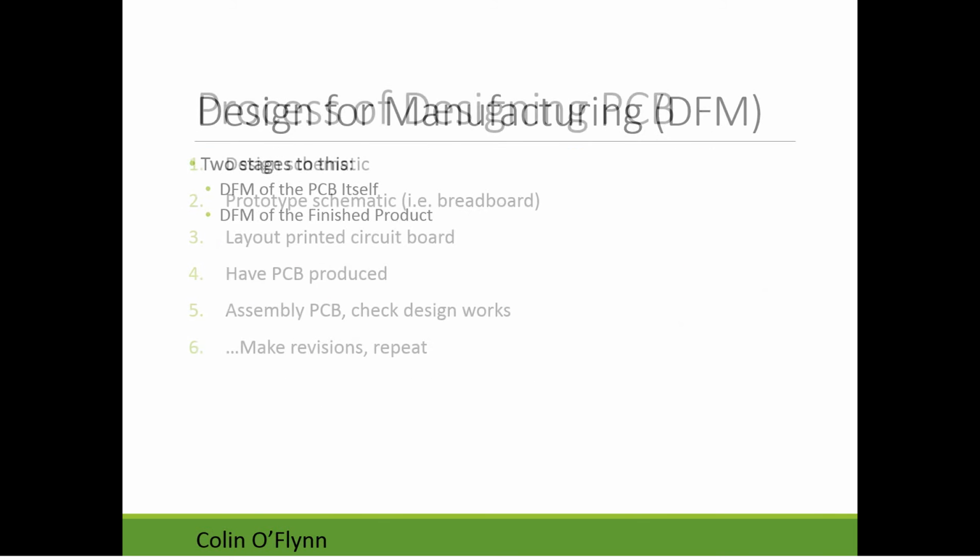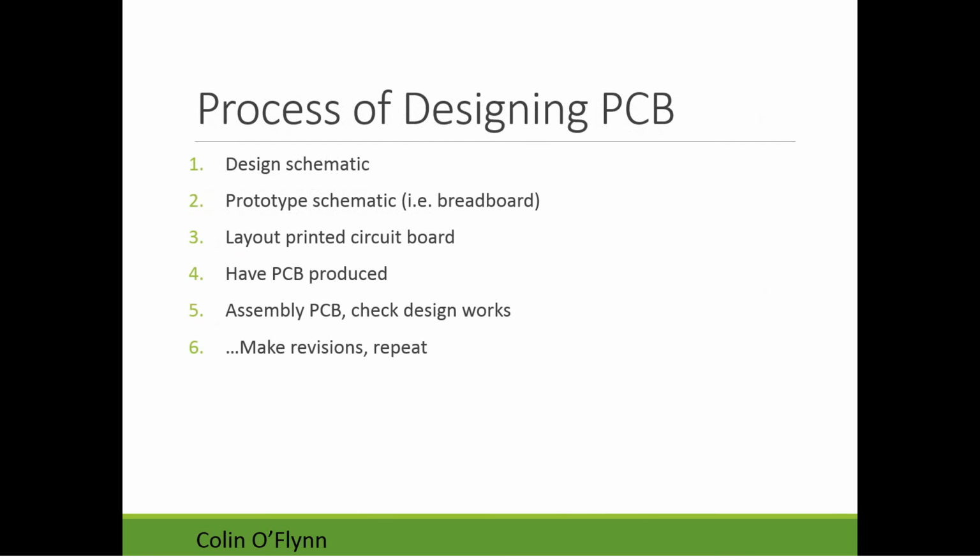So the basic process of how you end up with this circuit board is you're always going to need the schematic first. So you're going to prototype the design. Based on your schematics, you do the design, do the prototype. Once the prototype sort of works, you might lay out your circuit board and send it away, have it made.